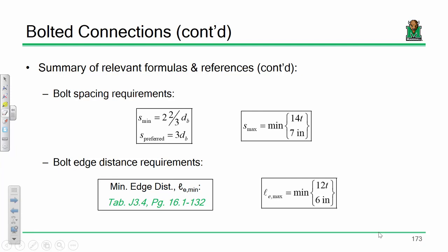And 2-inch bolt spacing versus 3-inch bolt spacing, if you can get by with 2-inch bolt spacing, I'd say go with 2, because that's just less steel that you need for connection plates and adjacent elements and so forth. There's nothing wrong with going with 3 times the bolt diameter, but I just take the opinion that if you don't need to waste steel, then don't do it.